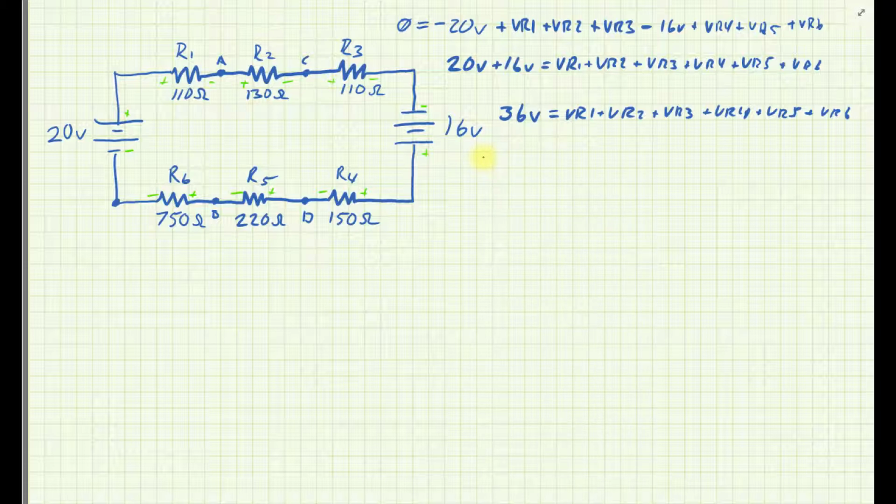Now, like I said, I mix and match my different theorems just to make whatever I'm dealing with easier. So I pick my favorite pieces of different theorems. And had I been thinking about this using just mesh analysis going into it, I may have said I loop times the sum of my resistors, right? So I times R1, I times R2, and so on, which basically just factors out to I times the sum of all those resistors.